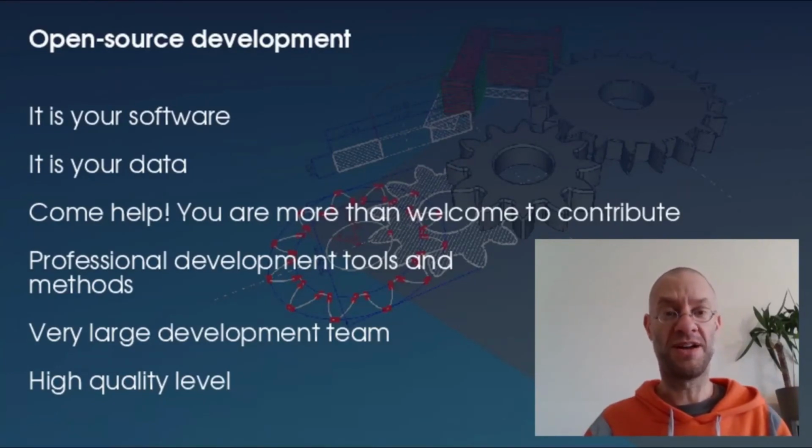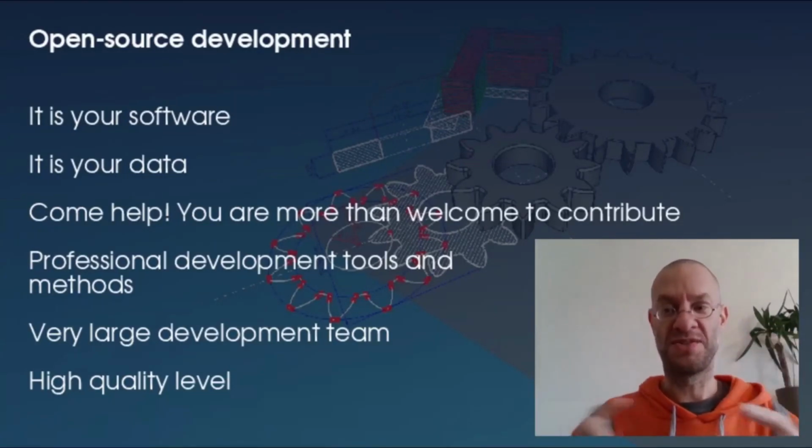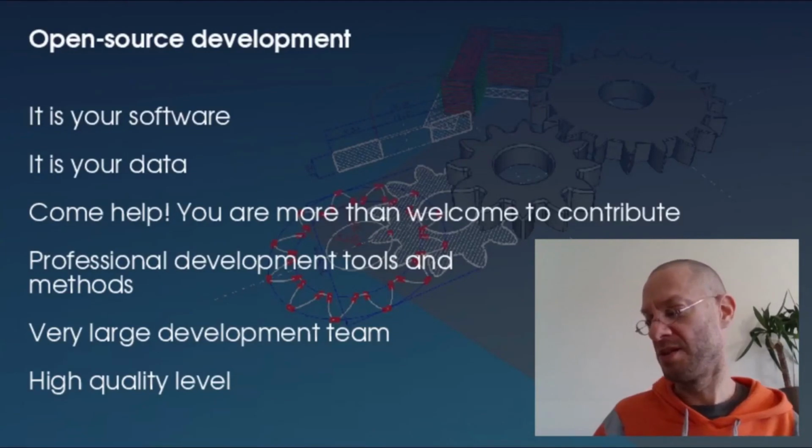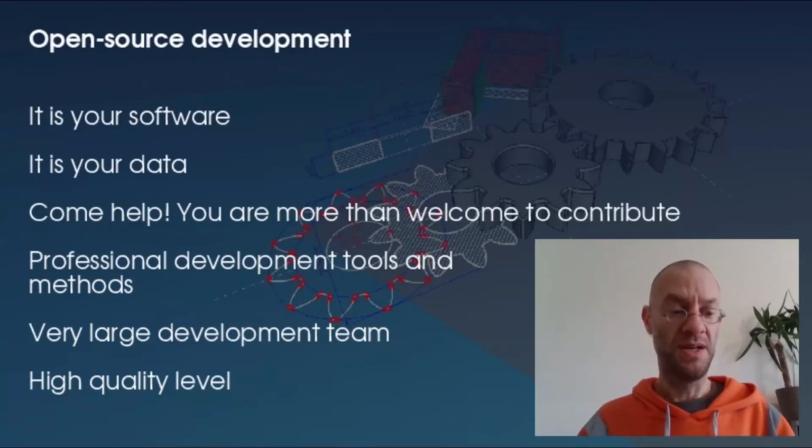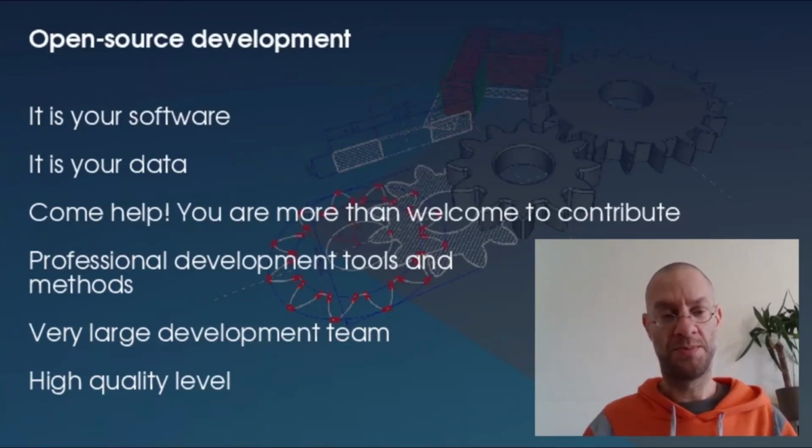FreeCAD files, FreeCAD models can be opened without FreeCAD. Basically the FreeCAD file is a zip. You can unzip it and take the components inside it. Most things are text-based files, and it's all open formats.